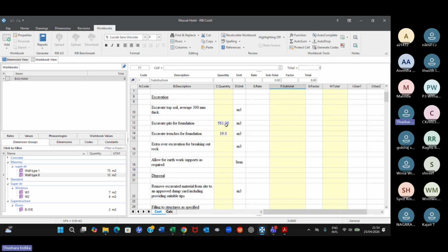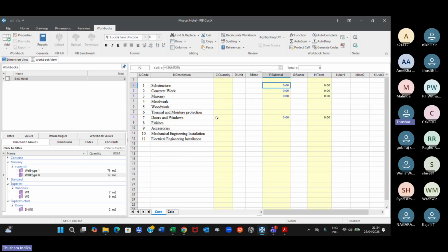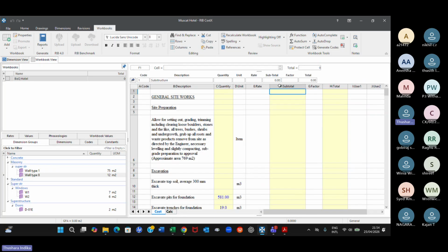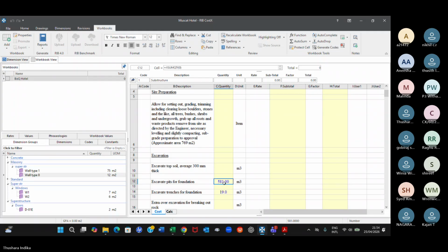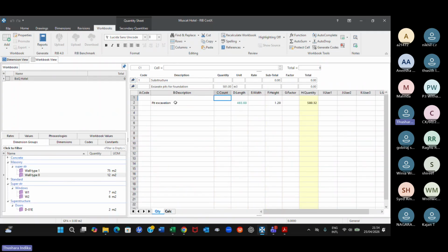How you change the decimals here in the BOQ. In the description, of course, in the measurement level, I have shown you how to do that from here. From here, you can change the decimal numbers, first decimal, round, and all these things. Okay, you can see here. You can change it. But as far as BOQ is concerned, this is a measurement level.